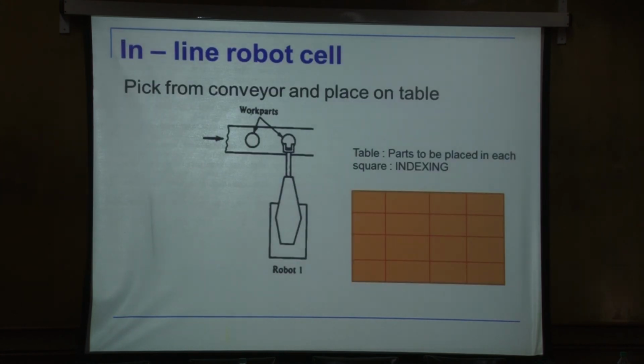So we can also write a program for this one with some sensor interfacing. So in the previous program there was no sensor interfacing. So we can simply use commands like sensor 1, sensor 2, on, off, and then to indicate when the part has come, when the robot has picked up the part. So when there is a conveyor also, when the part is coming on the conveyor, the moment we can put a sensor here, the sensor will sense this, and the moment the part comes, it can say signal 1 is high. The robot understands the part has come, it will pick it up and put it there. Okay? So that program also can be written, or we can simply add those few lines onto that program.